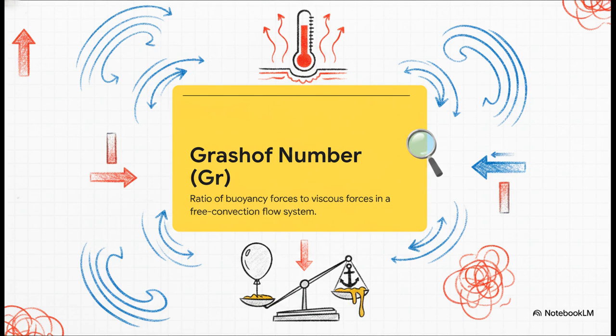This is a dimensionless group representing the ratio of buoyancy forces to viscous forces. If you remember forced convection, you might be familiar with the Reynolds number, which tells us if a flow is smooth and laminar or chaotic and turbulent. Well, the Grashof number does the exact same job for free convection. If the Grashof number is low, the flow is laminar. If it gets high enough, say around 10 to the 8th power for air, turbulent eddies begin to form.